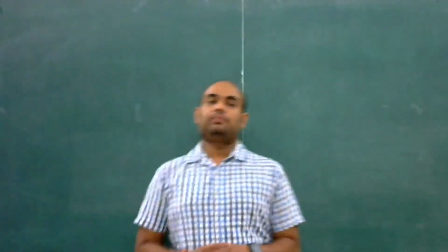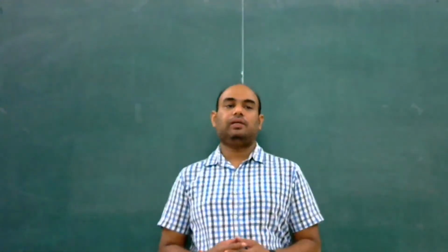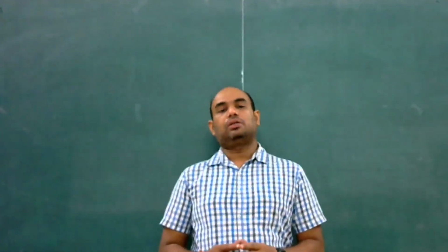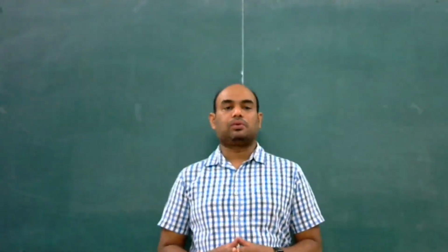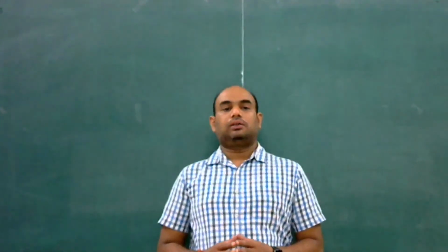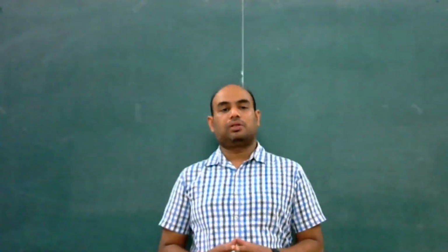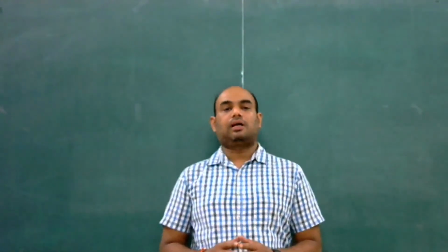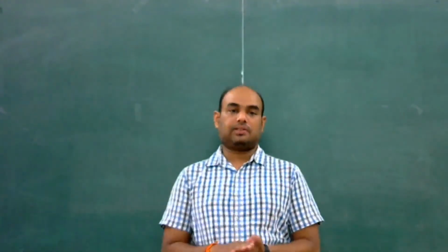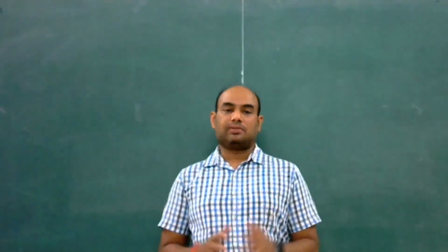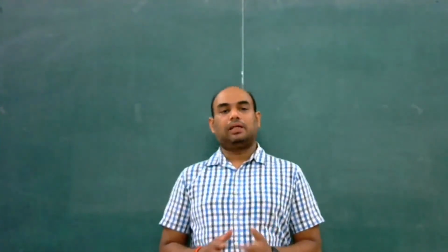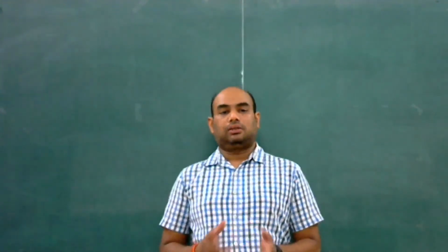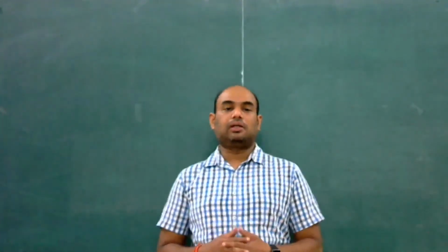So, good morning everyone. Today we will study transient analysis of synchronous machine using DQ0 variables. The transient behavior of synchronous generation is quite important because this analysis helps in determining the shaft stresses, winding and bus bar stresses, protective relay settings, and circuit breaker duties and their ratings.